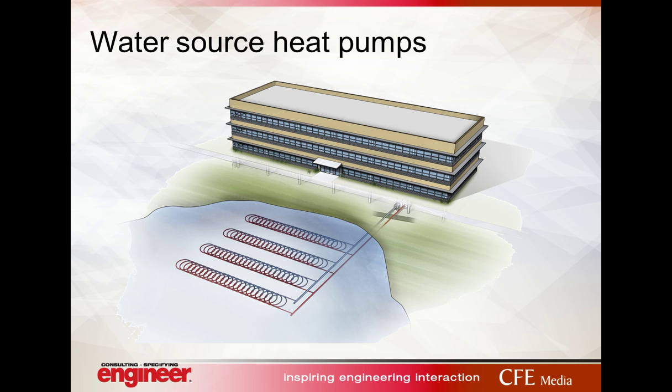The picture above depicts a ground-coupled water source heat pump system, or commonly known as a ground source heat pump system. But they could also be used with a cooling tower and a boiler rather than a well field. The well field is typically the large first cost item that makes or breaks looking at these systems. So if that's something you can eliminate, it might make the system more viable.